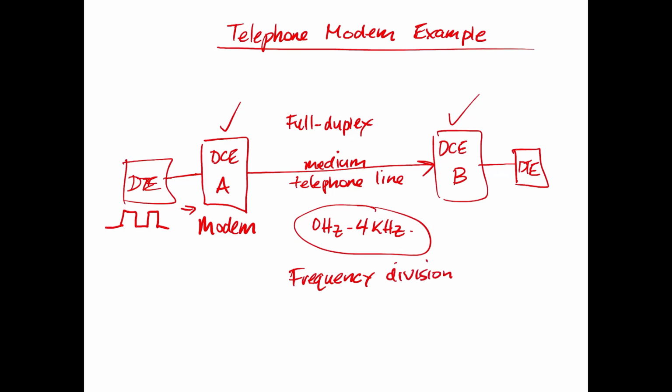So we just look for an audible carrier to send the information this direction. Each and every baud rate has a unique carrier designation. I don't remember what they are, but let's just pick, for example, a 2175 hertz carrier here. I know that's one of the carriers, I just don't know which one it's for. But that falls within the frequency band of 0 hertz to 4 kilohertz, and this is going to be the carrier used to move data as a frequency between DCEA and DCEB.